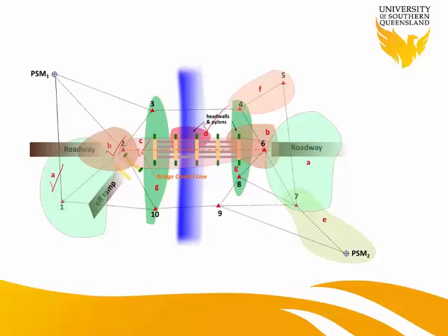Then after A, B, C, D, the next one is E, which basically represents the positional uncertainty. We all know positional uncertainty is with respect to the national system or national datum. Then we have F, which shows the survey uncertainty within the bridge control network. And then we have G area, which is here. G area is the control area for piers, pylons, and cross-section abutment control.